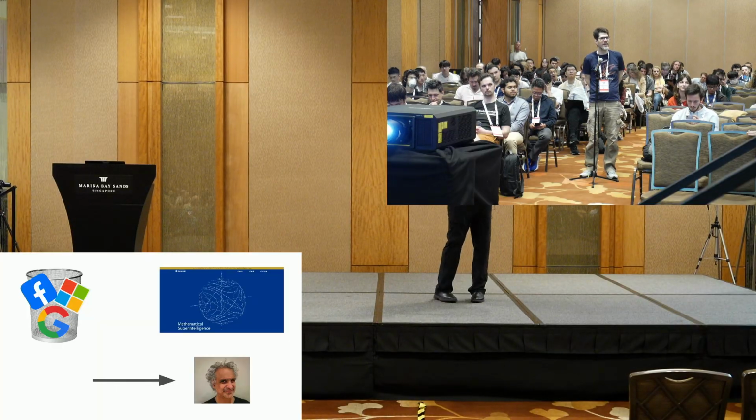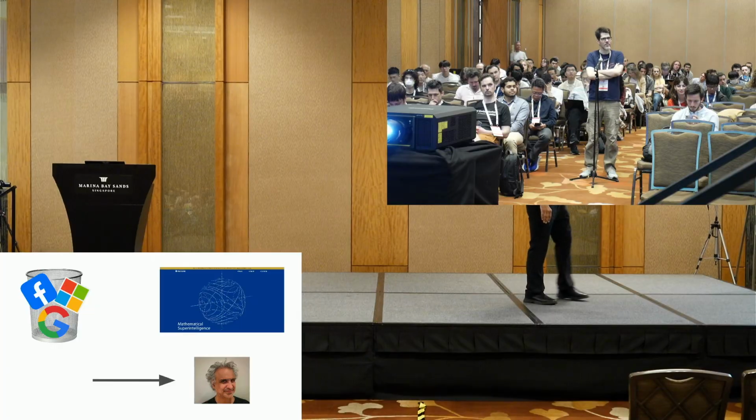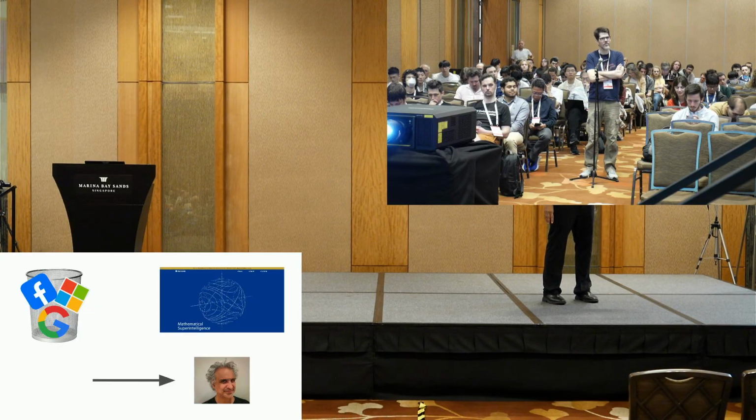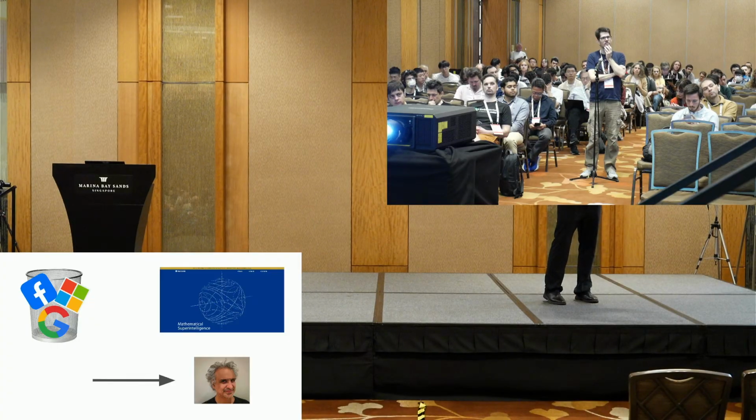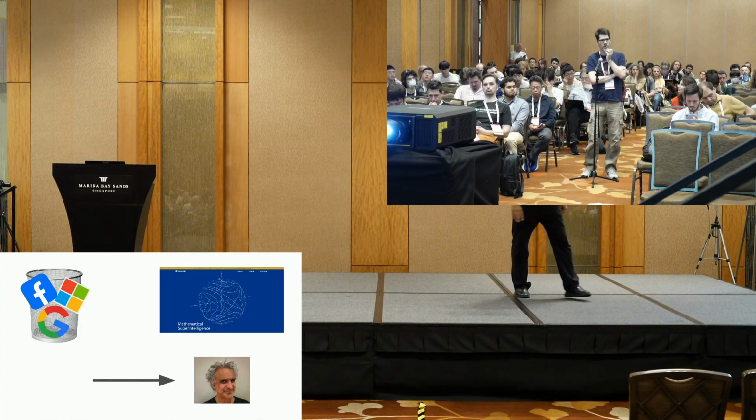In a far too small font on a slide, you had a bunch of combinators that have no layout associated with them, so they just get code generated that is automatically placed and routed by the system. And you have other combinators that do layout. So if you use Kleisli arrow, I didn't define Kleisli arrow. It comes from Control.Monad, and you compose that. No layout is computed. You have to use my special greater-than-minus-greater-than, and so you get to choose what you want to lay out and what you don't want to lay out. And so you can do the right thing at the right time. You have low-level control when you need it, and high-level control when you want it. Okay.